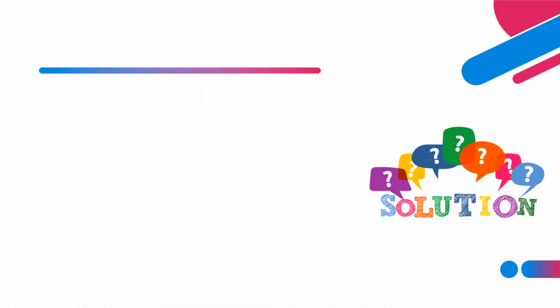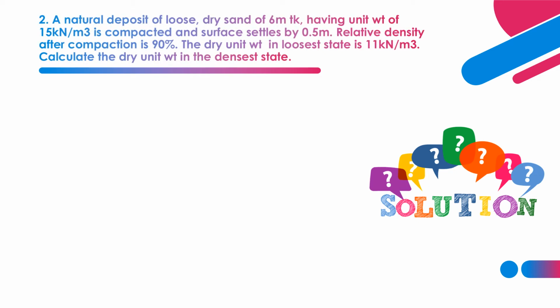Second question is a numerical answer type question. We just have to do some minimum calculations to get the answer. A natural deposit of loose dry sand of 6 meter thick. So for example, this is a strata 6 meter thick they have given, having unit weight of 15 kilonewton per meter cube, is compacted. So we are compacting a loose dry soil by some means, and the surface gets settled by 0.5 meter. So this is the settlement.